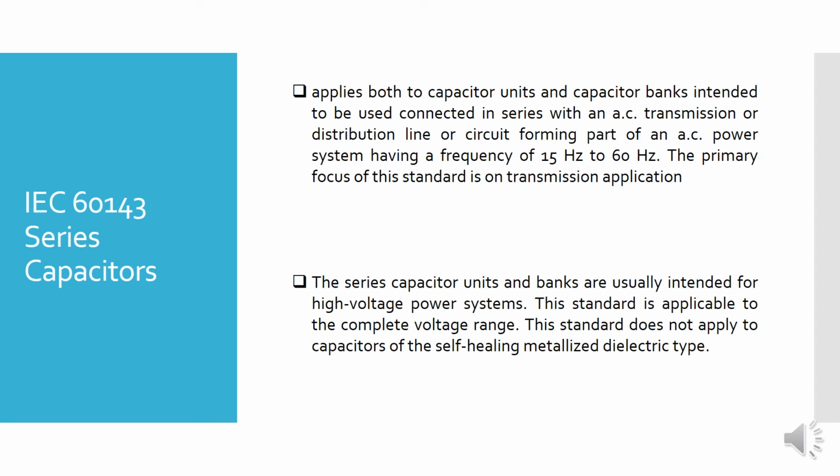The primary focus of this standard is on transmission application. The series capacitor units and banks are usually intended for high voltage power systems. This standard is applicable to the complete voltage range. This standard does not apply to the capacitors of the self-healing metallized dielectric type.